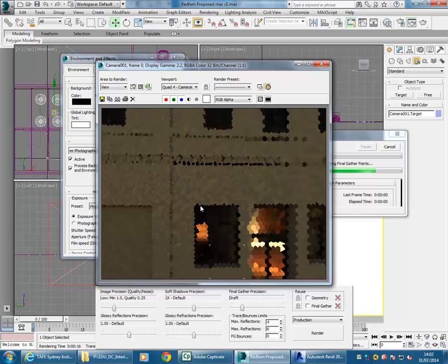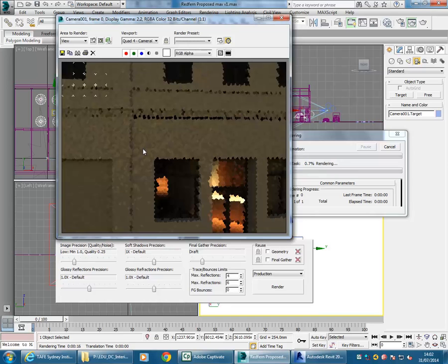Okay, so remember, these are still just draft renders for Max. This is low quality. In Revit it would be about medium, I suppose. Oh, beyond that. Yeah, exactly. But even this isn't too bad. You can get a pretty good idea of all the geometry. And notice I haven't done anything yet with the materials. These materials are coming from Revit. So you can do most of the initial setup of your materials that way in Revit, get them into Max, and then you can adjust them further.